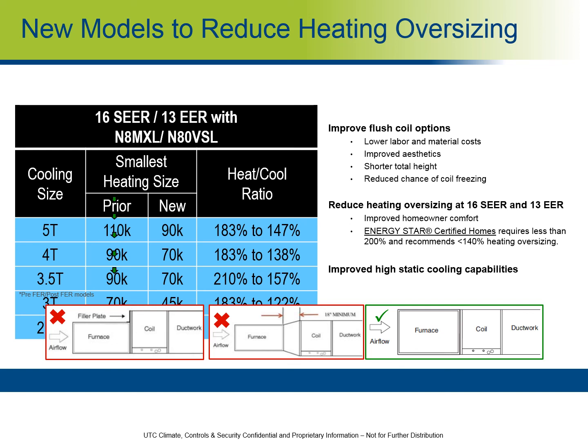So your limitations through the furnace itself or through the furnace and coil can typically create a higher static application. So now allowing the larger blowers with the smaller BTU ratings of the furnace allow for some of that static pressure to free up.